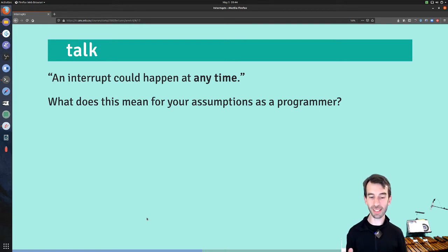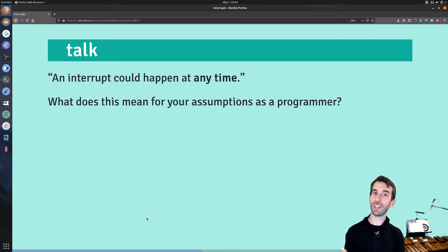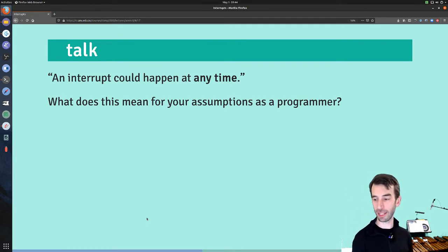The reason is that a timer interrupt is used by the part of the code which sends the audio to the headphone output, that play audio sample function. So if you start using the timer interrupt for other stuff, the main timer, then you might find that you've messed up the timing for the audio output. You just have to understand how that works, and we don't expect you to do it at this point.